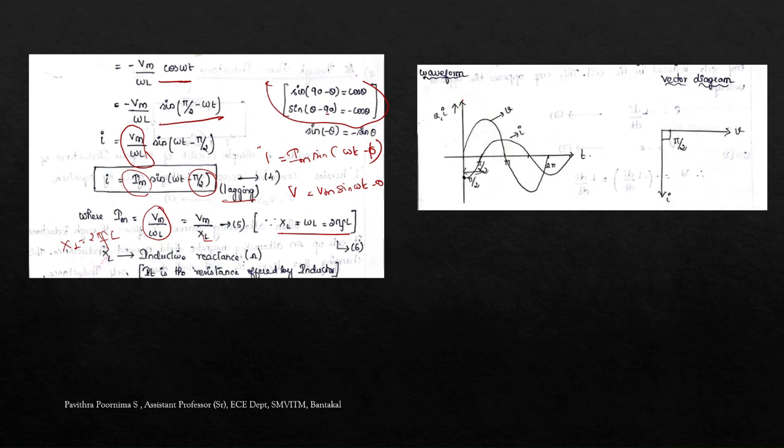Okay, so if we see the waveform for the voltage and current relation, the current is lagging by 90 degree. Which lagging? Current lags the voltage by 90 degree. Lags in essence means a delay. So voltage has the angle 0 degree, right? Vm sine omega t, in the place of angle nothing is there, so 0. So it starts at 0, pi and 2 pi. But what about the current? It lags the voltage by some angle, pi by 2.